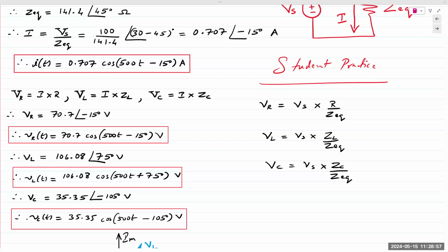All right, then we found the resulting current I. That same current I is flowing through all four components. Now, if we wish to find the inductor voltage or the capacitor voltage, you can perform differentiation. Chapter 3, VL is L di over dt. You can differentiate this current and find the voltage that way, or you integrate this current and find the capacitor voltage. But thankfully, we don't have to do it.